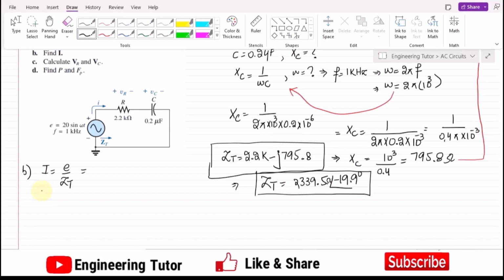So in order to convert it into the polar form, I should have the RMS value. To convert the peak value into the RMS value, I have to divide it by the square root of 2, and divide it by Z total. The angle with it is 0 degrees here.